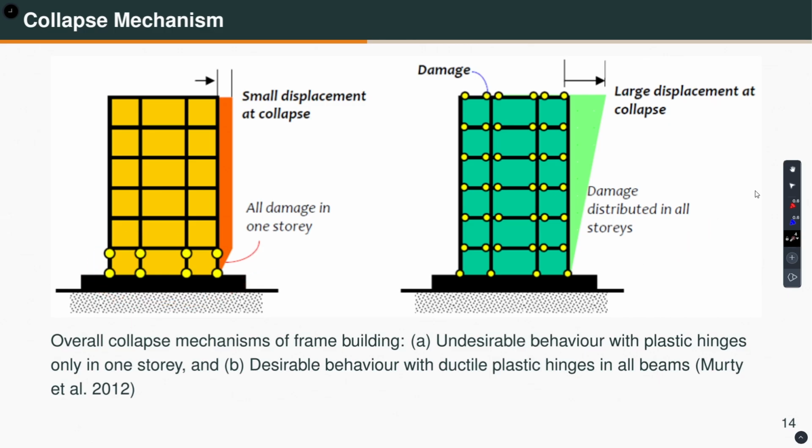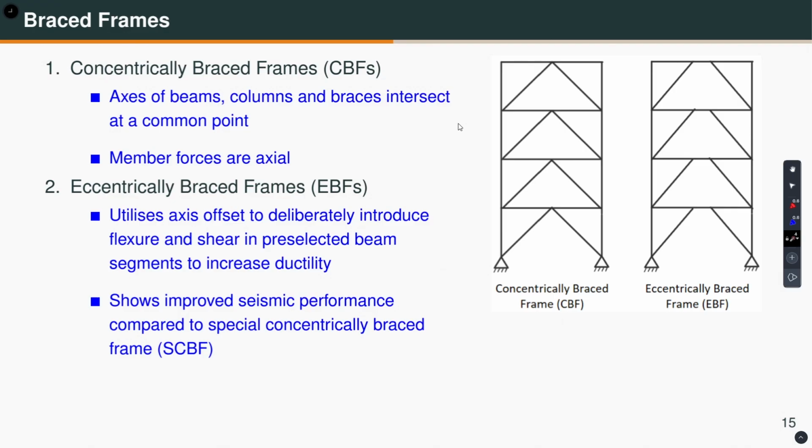So, as you can see, the plastic hinges are going to form at the ends of the beam. So, can we concentrate our attention on modeling this hinge behavior at the ends of the elements, whether it is a beam or a column? For modeling we should do both, we should make sure that there are no hinges forming at the column, unless you model you would not know. So, with that we will get into the concentrated plasticity approach, but before that let me talk quickly about the other system also.